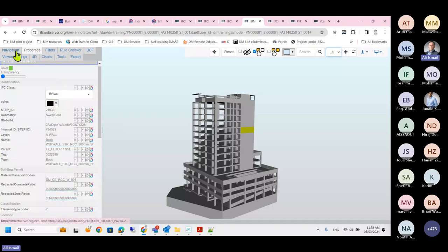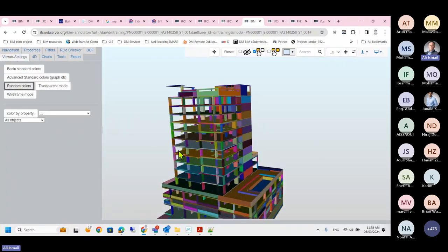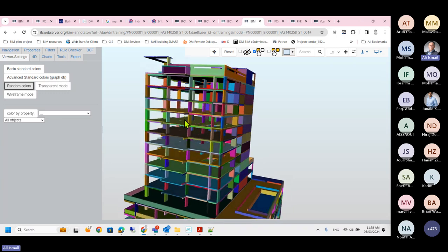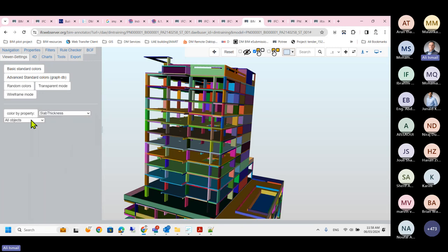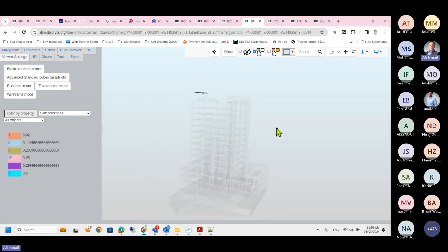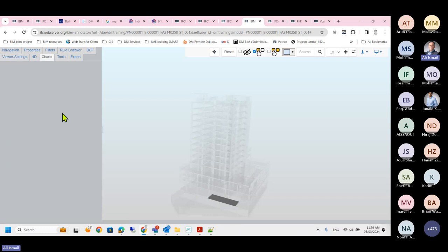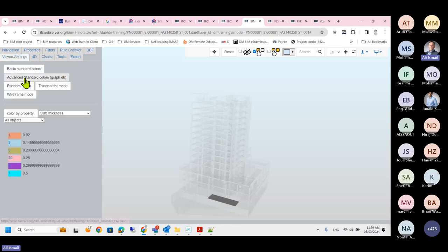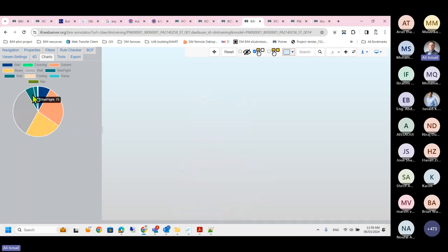and to do many things, to visualize, for example, using random colors, how the granularity of this model is done, to filter, for example, elements by a certain slab thickness. So here I will have the possibility to quickly visualize or understand the model, how many slabs. So this is where there is some flexibility, or to see many pieces of information, or filtering using class.